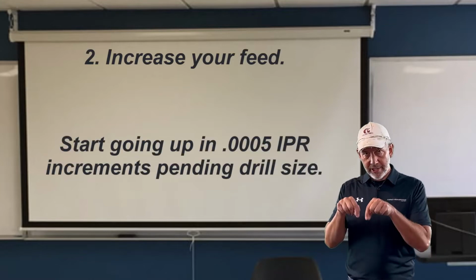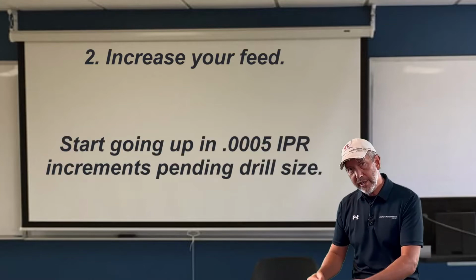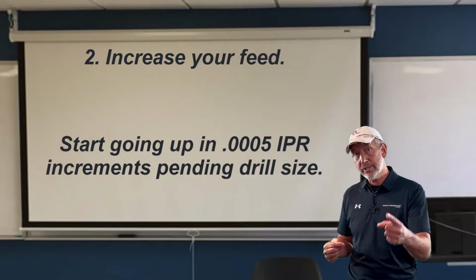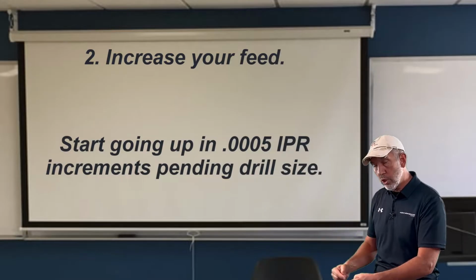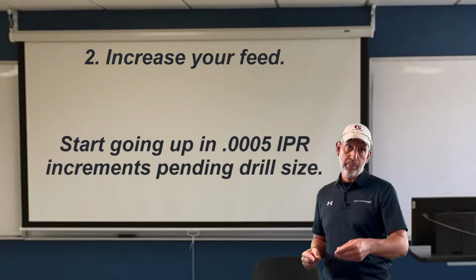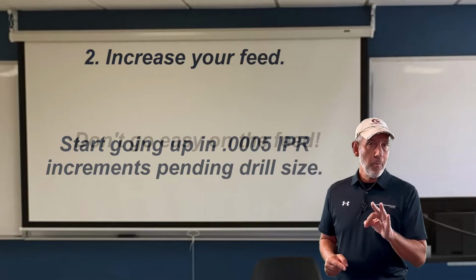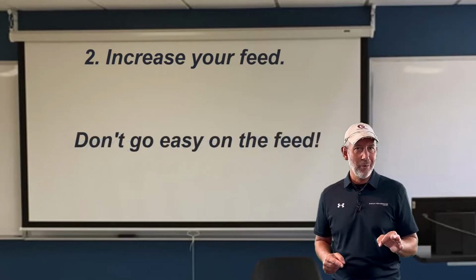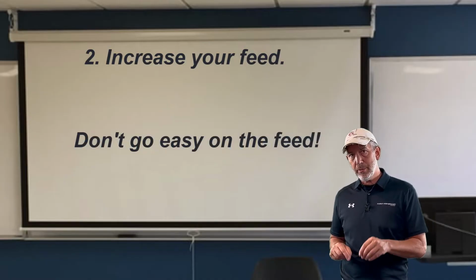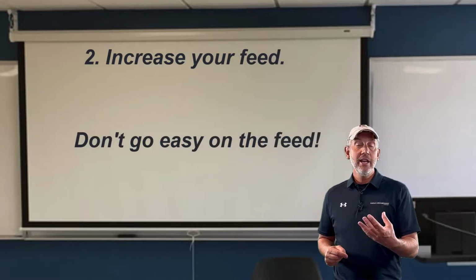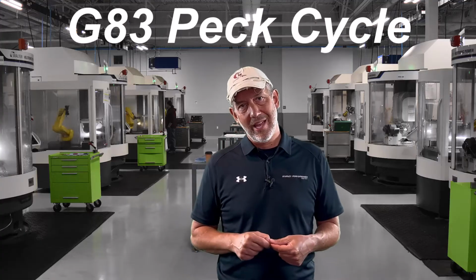Anytime you feed a drill a little bit faster, you get the curl on the chip. The material you're making from the cutting edge will curl quicker and it'll break. So don't baby your drills. That's one thing I want to tell you. Don't baby them. Make sure you feed them good enough to break a chip. Now, if that's failing, and let's say the coolant through is not doing the job, the feeding's not doing the job, what we might have to do is something called a peck cycle.